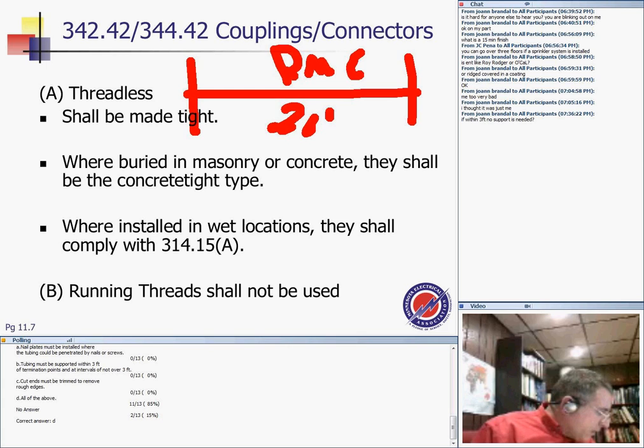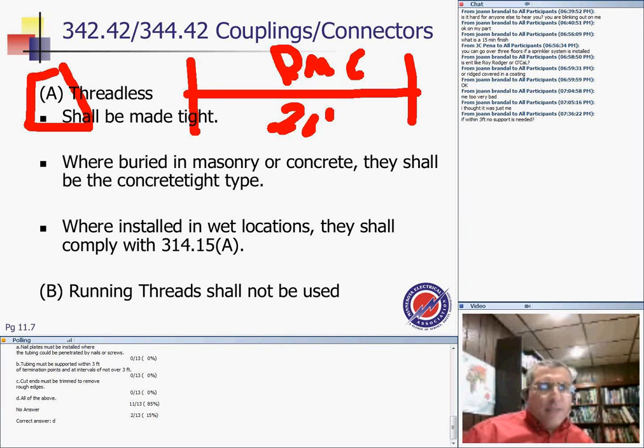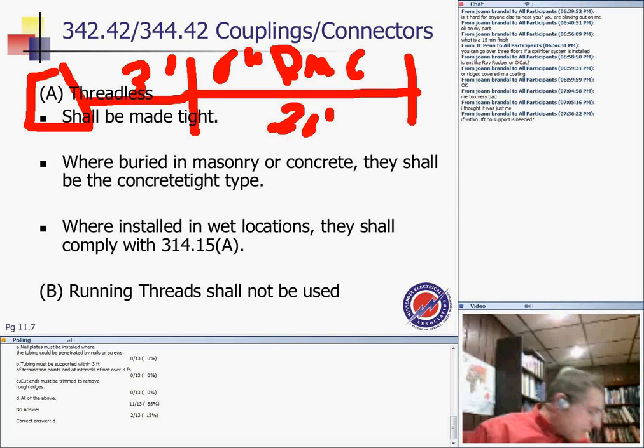The whole table for it. Every 3 feet, they can go up to 5 feet. Fastening shall be permitted to be increased to a distance of 5 feet where structural members do not readily permit fastening at 3 feet. So for the most part, every 3 feet. If I have a conduit box over here, my 3 feet for the most part, and the conduit is a 6-inch conduit, then I can go 20 feet after that. If it's a quarter of an inch, 10 feet, and there is 12 and so forth. And there's some exception if you go vertical, guys, a riser, 20 feet and so forth.